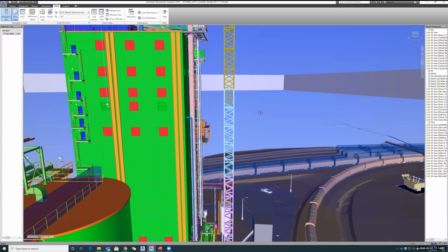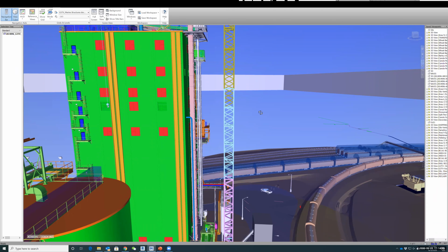Okay, let me tell you guys, we don't know how many clashes we have in this model, because every time we run everything, every single computer just froze because there are so many clashes. But I can give you some understanding. Autodesk provides a default model, a very simple school project, 3 levels. That's the school in Germany, provided by Autodesk. It's supposed to be a good model, right? That model contains about 3,000 clashes. So we don't know, but it's definitely more than 10,000. My guess is probably 100,000. So your task will be very easy.